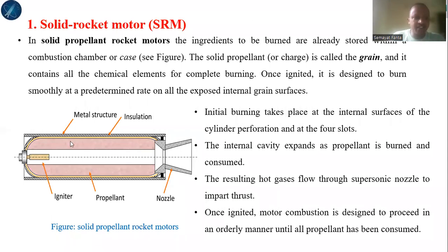Okay, so for that purpose, a solid rocket motor consists of a casing that covers the overall structural system. This is a solid rocket casing. And then you can see another small thin layer here with some yellow color, which is called the insulation layer. Insulation must be selected in the proper way, because high heat from the combustion chamber is there. That should not come out to the casing. If it comes out to the casing, it immediately collapses or damages the casing. So the casing must be protected from any kind of temperature which comes from the surface. So we need heat protective material or insulation material.